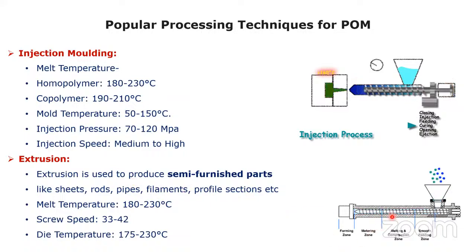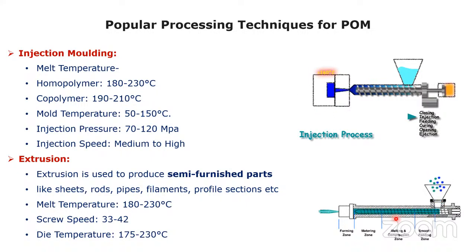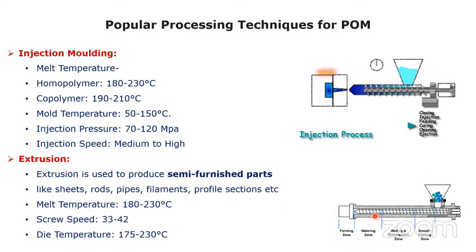Metering is nothing but, see, in feeding your material will get fed. That material will get pushed forward and melted in the melting and compression zone. Then that material will move forward into the metering zone. In the metering zone also, your material will get mixed in a proper way with the help of shear action.